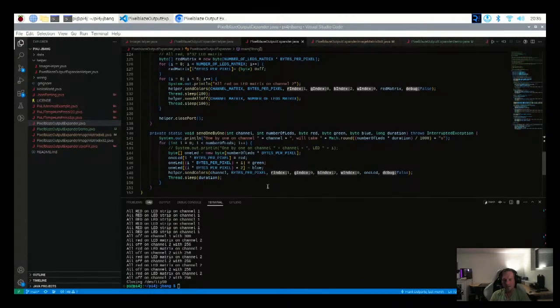I think we should explain what that means, because that can be an issue. I have been doing web programming and video stuff for, I'm getting old, so a long time. And it's always been red, green, blue. Red is first, then green, then blue. And when I started experimenting here with this Pixelblaze thing, I didn't get the right colors. It just didn't match what I was expecting. And it turned out that for some reason, they are not in the same order. So green seems to be first, then red, and then blue. Or I totally misunderstood something.